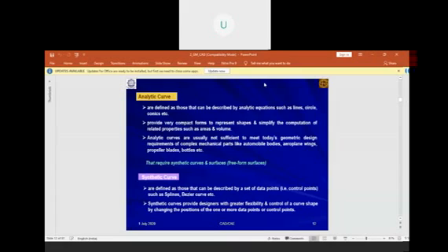But analytical curves are usually not sufficient to meet today's geometric design requirements of complex mechanical parts like automobile bodies, airplane wings, propeller blades, bottles. For that design, if you use an analytical curve, it is not as aesthetically beautiful, or sometimes you have to compromise the shape which is given through your aerodynamic calculation. So that is why there is the birth of synthetic curves, which are basically described by a set of data points or control points.